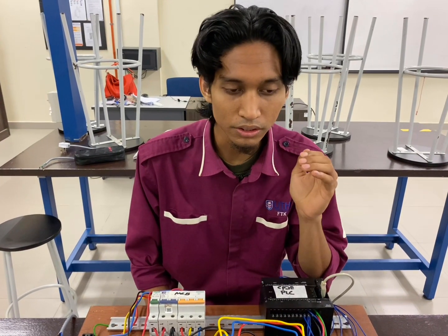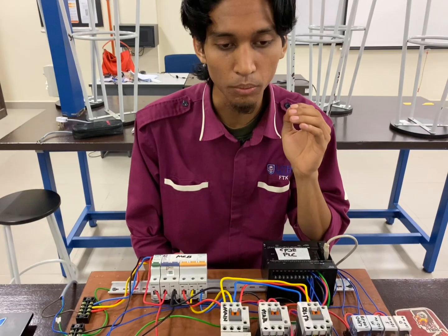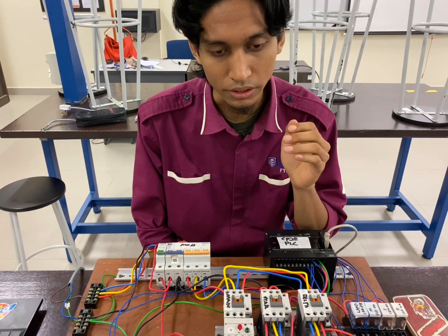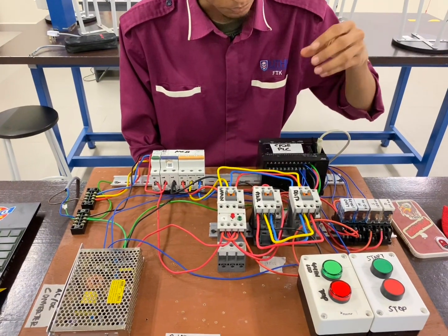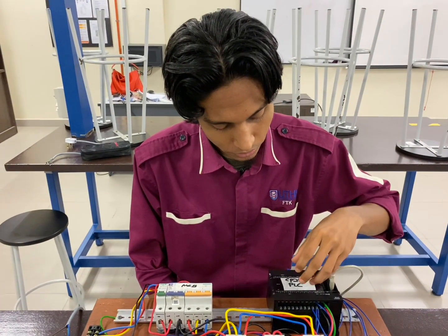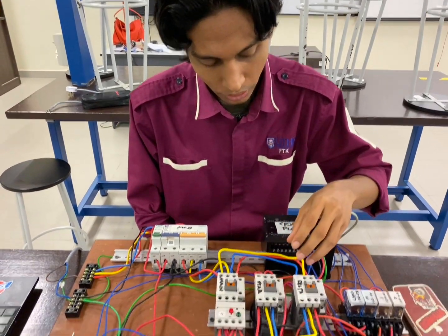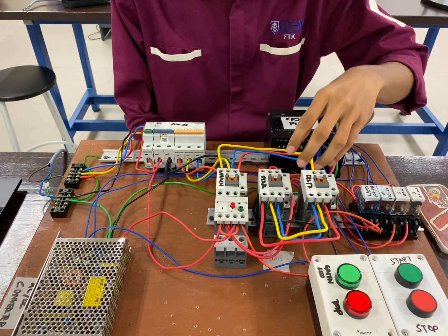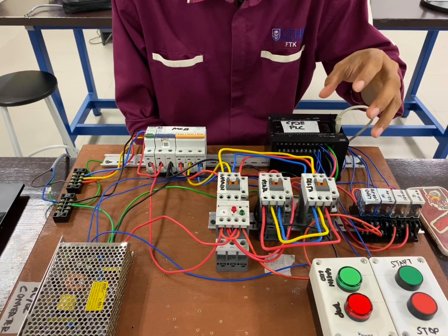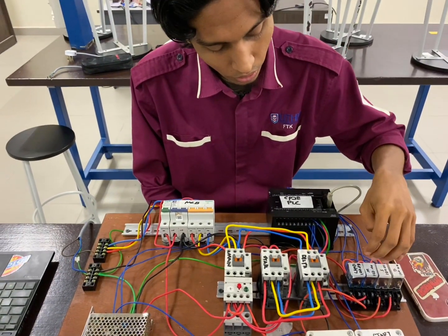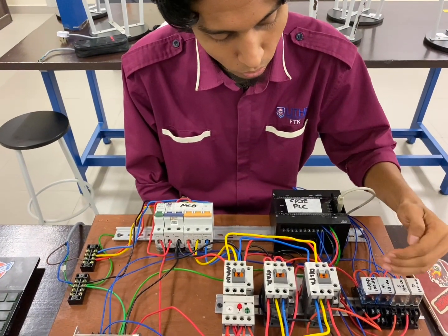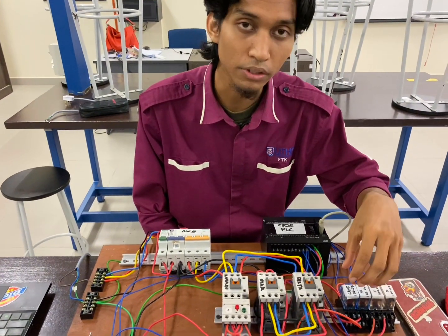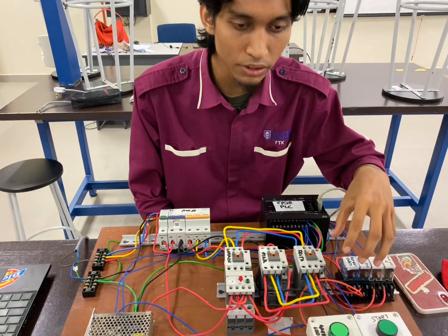The second is to design the star delta connection without PLC and with PLC connection control. If you use a PLC controller to make a star delta, we need a relay to give the command to the contactor. If we don't use the PLC, we will not use the relay, and we will use a timer instead. That one is robust.